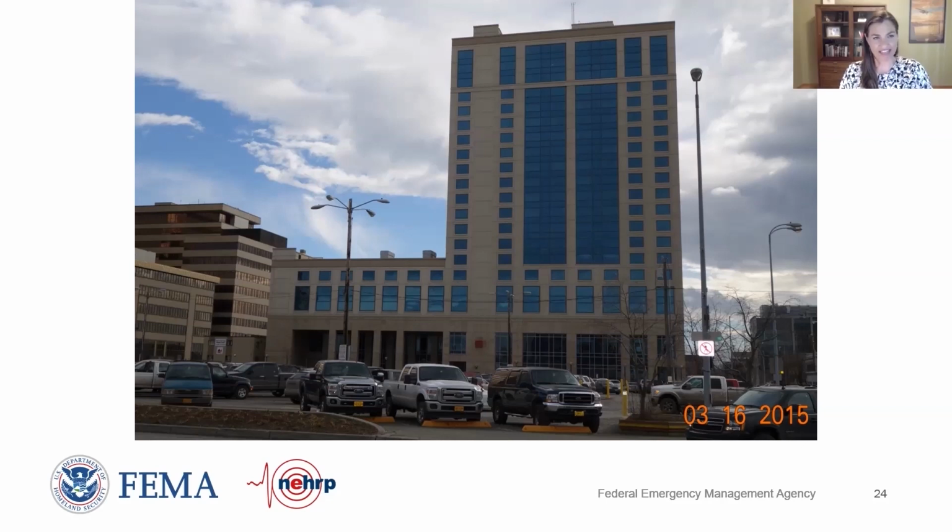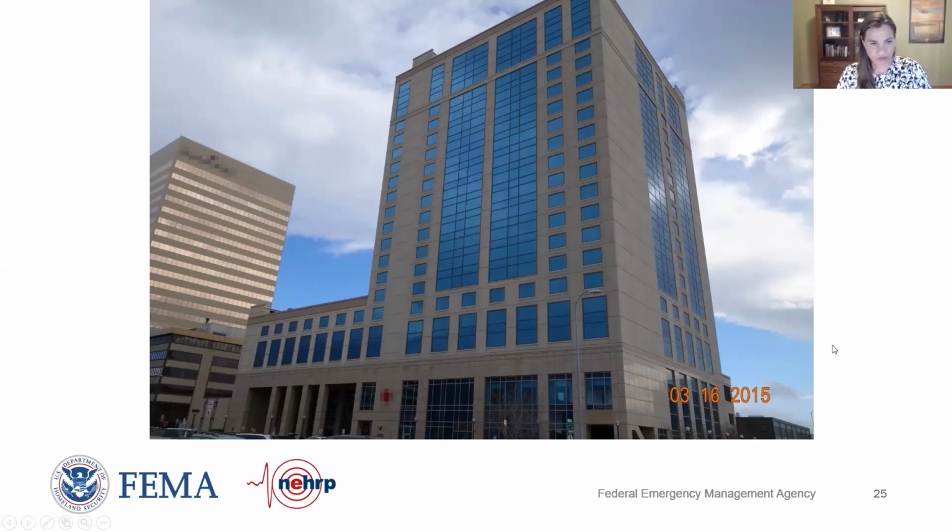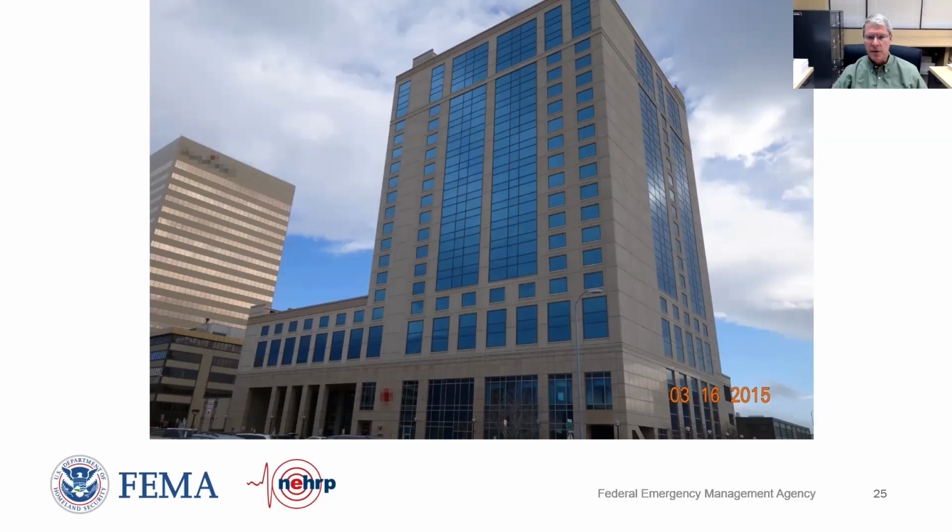Looks like a vertical offset, so we've got an out-of-plane setback. Yes. On this face, let's walk around the other side. We're down to the right-hand side of this same view, but looking up. The taller lower story versus the upper story looks like a weak or soft story, a vertical irregularity at the base, right? Yeah, we have a taller story.